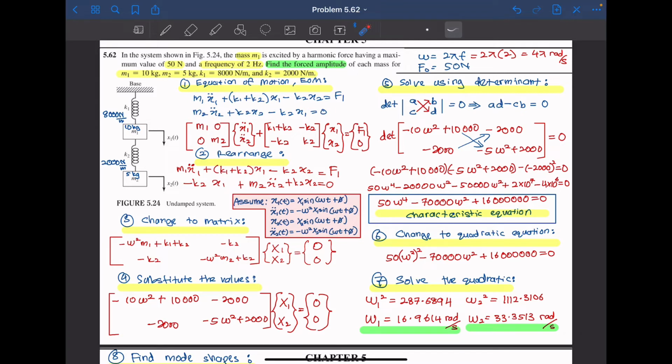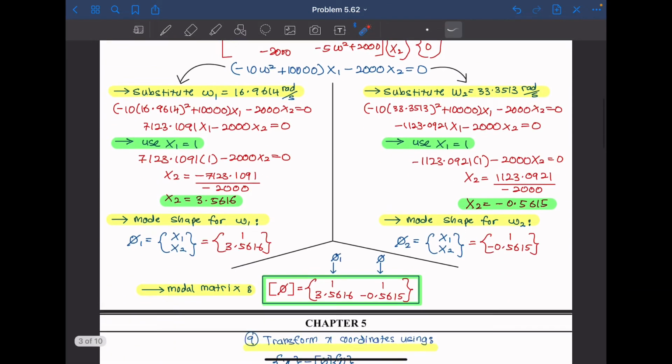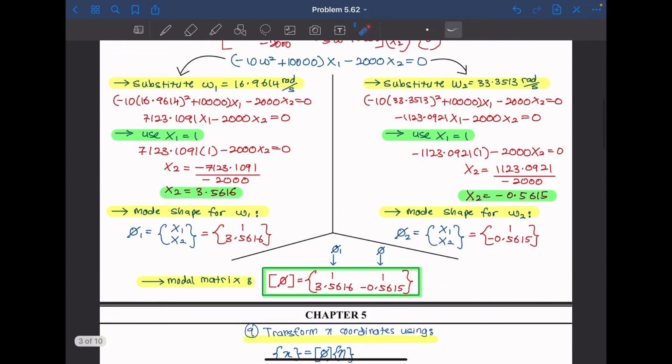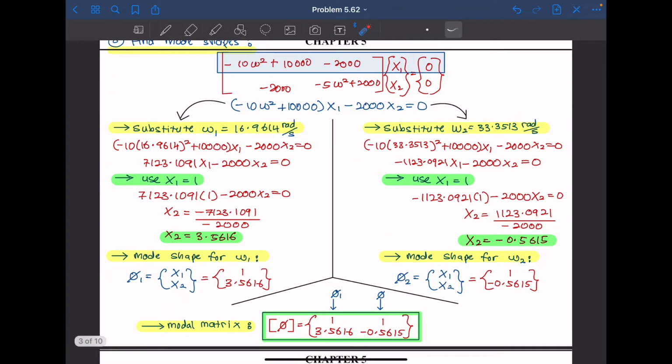So basically this is already coupled, as you can see if you refer back to your slide, the slide already explained about the couple. So now we want to decouple the system, from one 2 degree of freedom system into two single degree of freedom systems. Okay, separate. We want to separate. So from coupled to uncoupled. So now we have to decouple them. So that's why we use modal analysis.